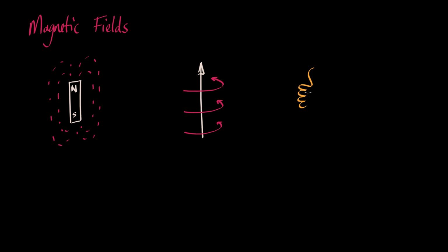Give yourself a thumbs up. If your thumb is the wire and the way it's pointing is the direction of current flow, your four fingers point in the direction the magnetic field curves around the wire. We'll call these individual curves Amperian loops.